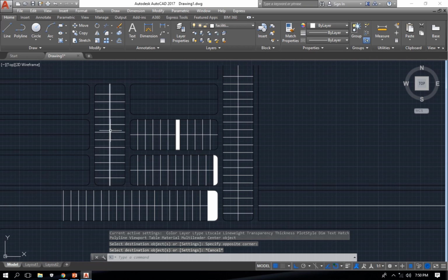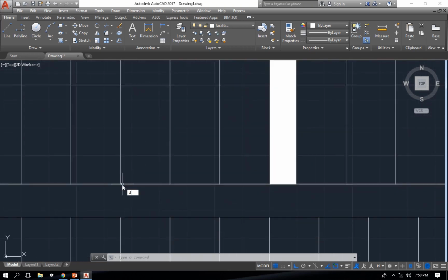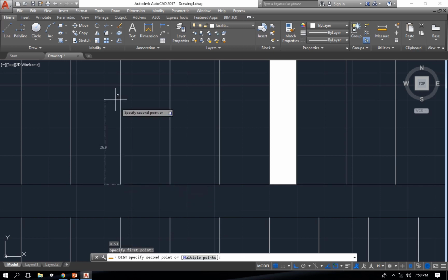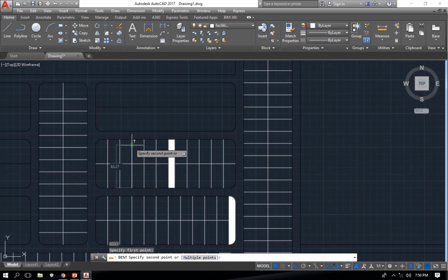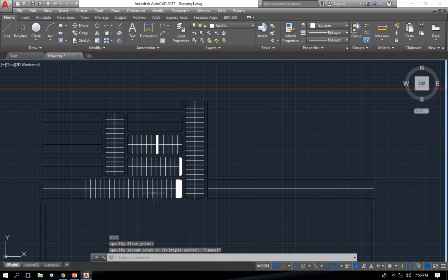So you notice that each of these blocks, if we have a distance of 18 here, of 36, sorry, and you have 18 here, this suggests that every block is 72 meters because we have 36 on one hand and 36 on the other. So that's going to serve as a guide for you in your course of subdividing.